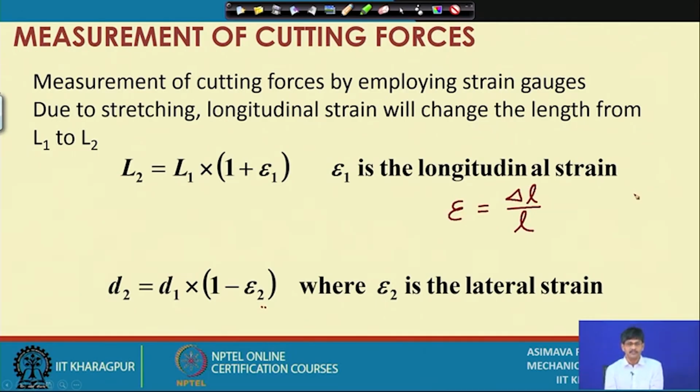stresses which have arisen in the workpiece or the part of our interest due to the forces which are applied, tensile forces giving rise to tensile stresses. So, this is tensile strain. However, if we assume, we can generalize it also, say the cross section of those strain gauge wires is a circular cross section, in that case that will generally undergo a compression. But